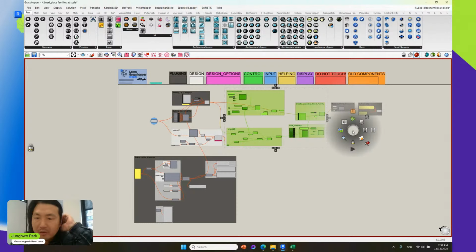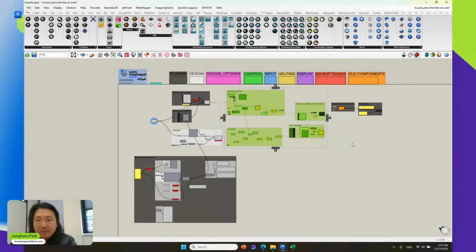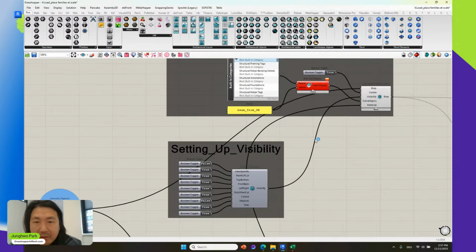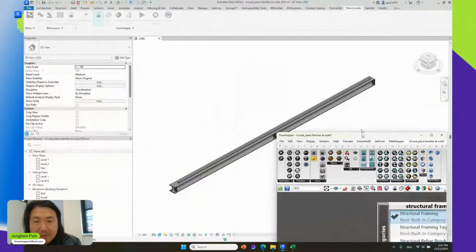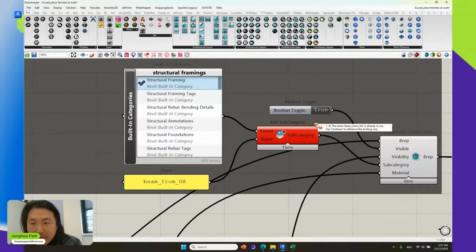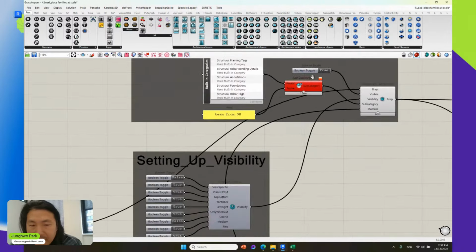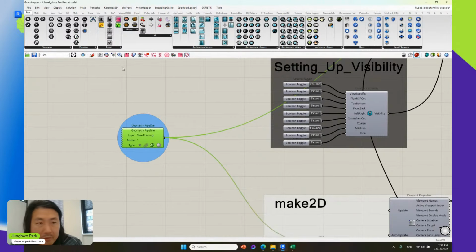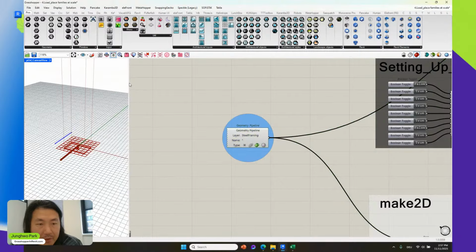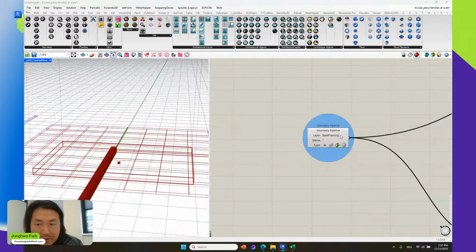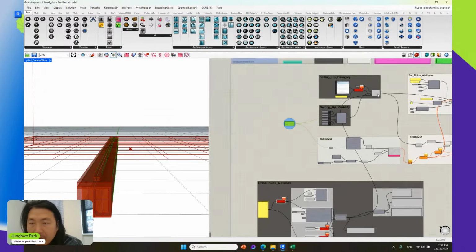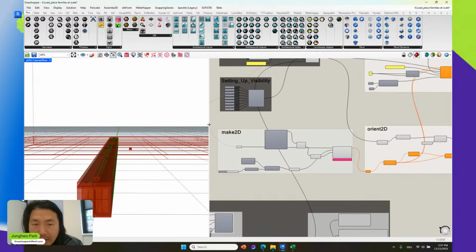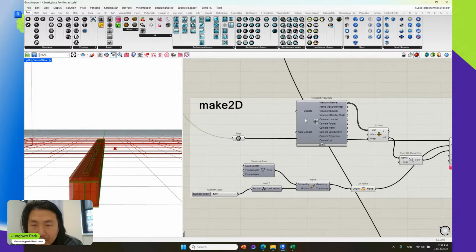So let me launch this. I'm just enabling it. So now we can see, because this subcategory, beam, already exists in the example, it shows as a warning, but it's not an error. What we're going to do from Grasshopper is read this geometry, which we have in Rhino, and convert it as a BREP. And now, as I said, we need to create a kind of 2D representation.